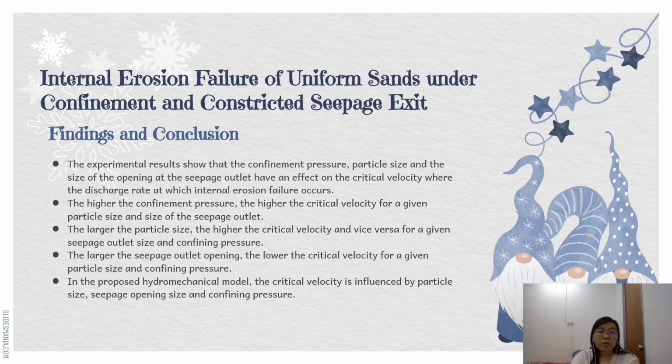erosion failure occurs. The higher the confinement pressure, the higher the critical velocity for a given particle size and size of the seepage outlet. The larger the particle size, the higher the critical velocity, and vice versa, for a given seepage outlet size and confining pressure.